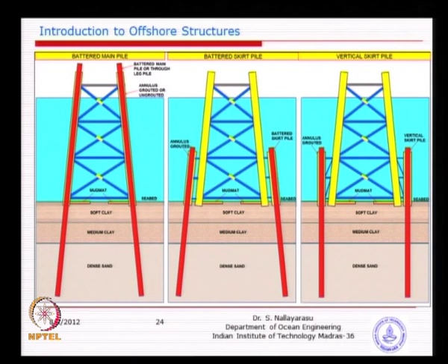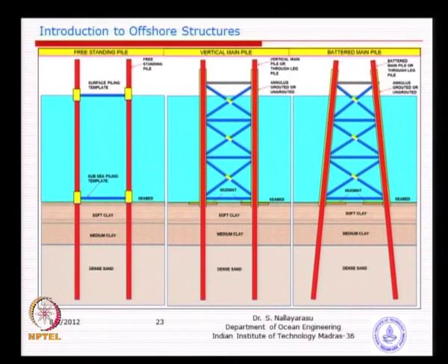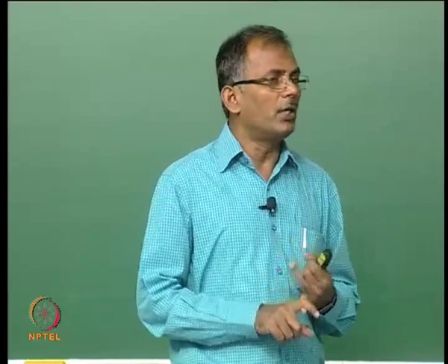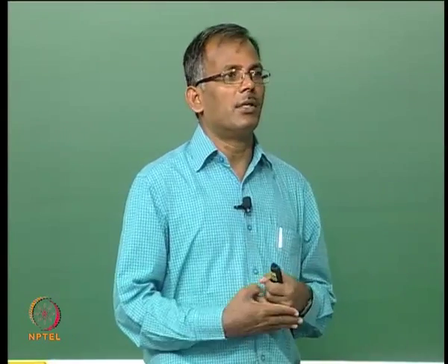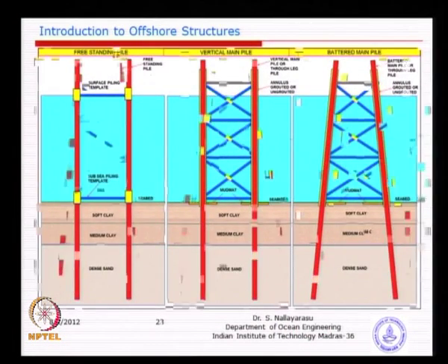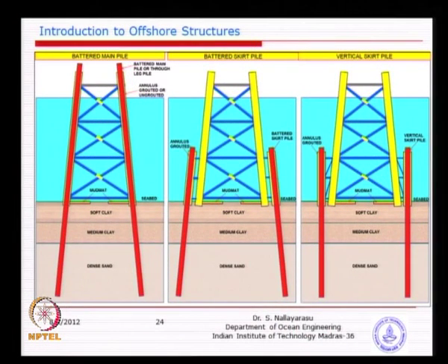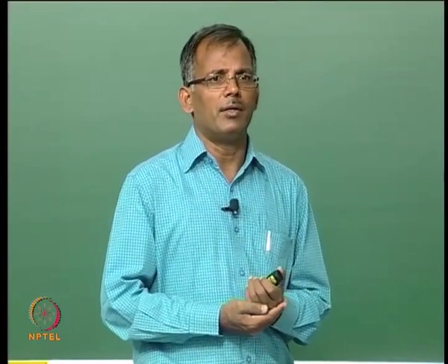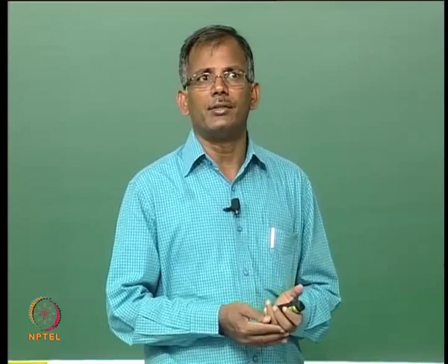You have both of them, vertical and inclined. In the last one we made the pile vertical, which facilitates the installation to quite a great extent. So you can see from the last 2 pictures how thinking was put together constantly to improve and reduce the cost and reduce the risk in offshore installation. So basically this jacket design is not something new, it has been there for several years and decades, and in fact it has become a very simple project nowadays for jacket design.